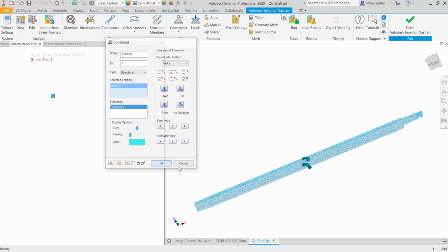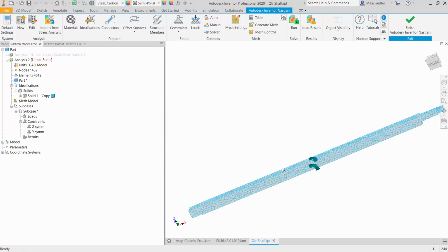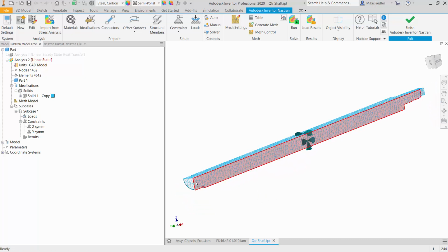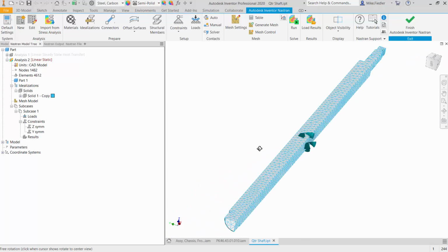Right, so now somewhere in the model, a linear static stress model needs to be statically stable, right? So now we have Z constraints on that face, we have Y constraints on this face. So down at this end of the model, what I'm going to say is it doesn't matter. Either end face, I could select the faces there and apply an X condition, right? So if I hold this end of the model X fixed, then if it's all contracting overall, it'll all move towards that constraint. If I select this face, then everything will move towards or away from that face. So it doesn't really matter in this case which end I take here.